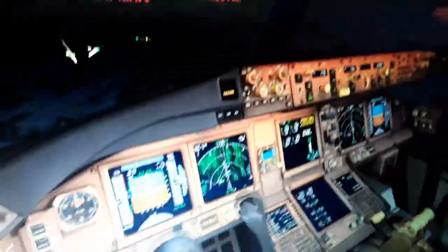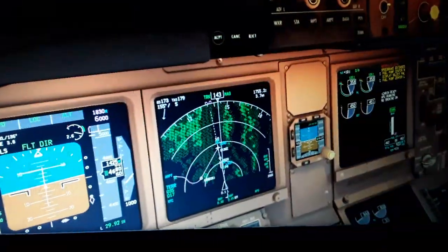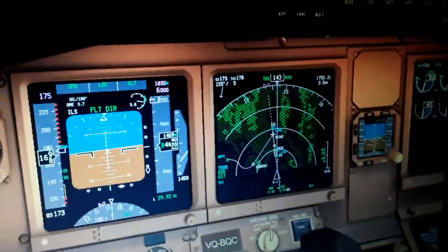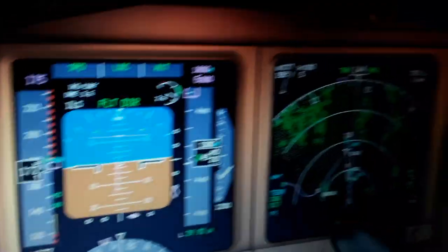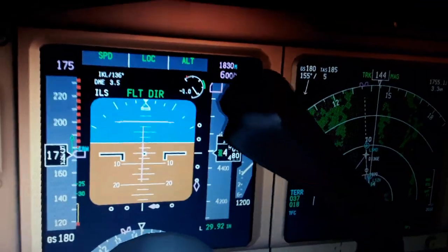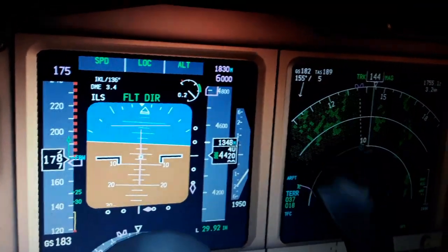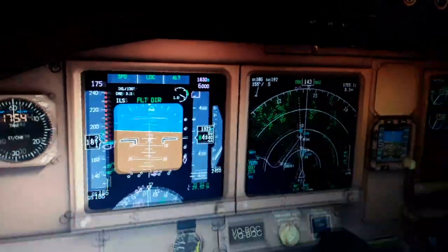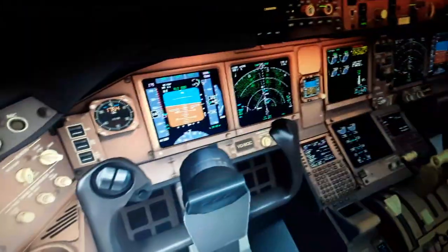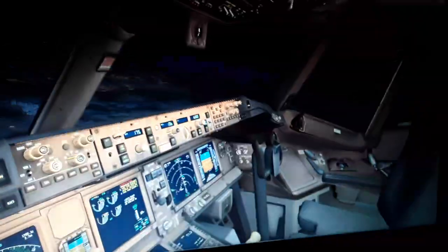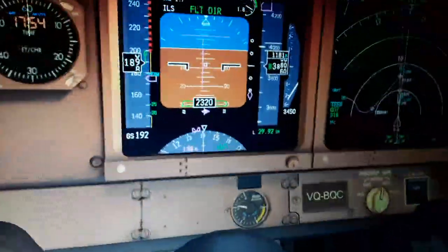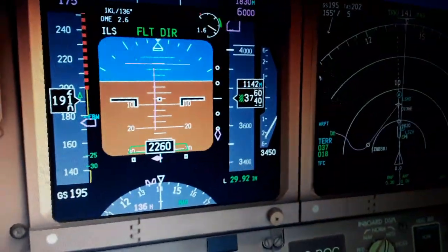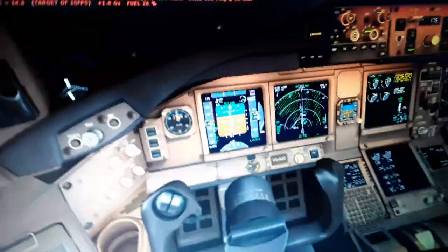So we have the LSZH localizer here. You can see this is an LSZH localizer landing. So we are aligned with the runway, the LSZH localizer, and also the glide slope. Okay, you'll see the radio altitude above the ground level in a couple of seconds as we keep descending. So we are at 2500. We have the radio altitude 2500 feet above the ground level.